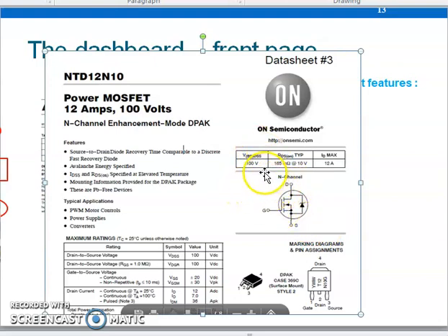You cannot put this kind of device into line voltage, which is 230 volt. It's stated here the features of this device and typical applications, usually used for this kind of MOSFET inside pulse width modulation motor control circuits or supply converters and whatsoever.